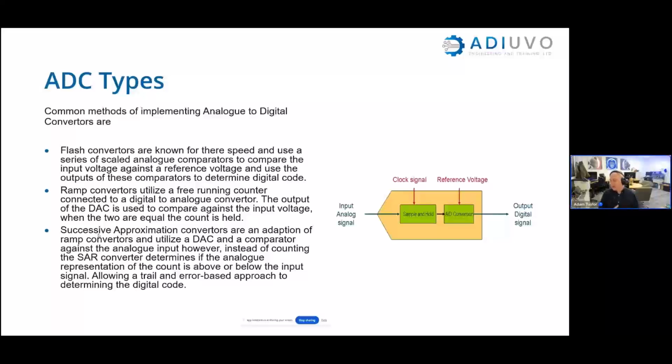The key thing is we're going to put in an analog voltage and we're going to receive a quantized digital signal out of this that's going to be several bits wide for each sample. Once we've got this, obviously, it gives us a lot of immunity to noise.